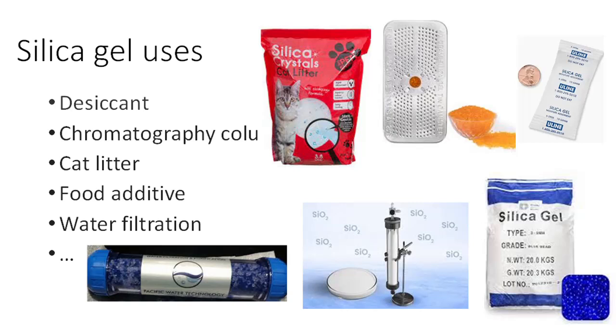In terms of moisture absorption, we could say that silica gel can absorb up to 40% of its weight in moisture, significantly lowering the relative humidity in a closed container, often to about 40% RH, or relative humidity. This makes it an ideal choice for preventing damage to products sensitive to moisture, such as electronics and foods. Reusability. Once silica gel becomes saturated, it can be regenerated and reused by heating it to about 120-130 degrees centigrade, which drives off the moisture.